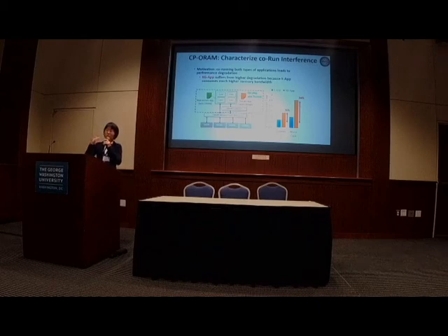So the buffer on board design is very good for expanding your memory capacity, because you can have one buffer on board interface connecting with the CPU, but after this interface you can connect them with multiple parallel channels. So we propose that we can offload the heavy computing part of this ORAM, the main computing of the PathORAM or ORAM controlling part, to the buffer on board architecture, and then this processor is only connected with the rest of the memory from that buffer on board controller through the serial link.